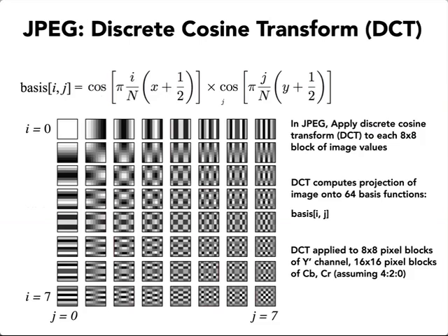So that's big idea number 2 that I described originally: put the compression into luma or luminance rather than chroma or chromaticity, which are equivalent, at least for our purposes today, technically. The other idea I said was that the human visual system is less sensitive to compression error or image error that's in high frequencies as opposed to low frequencies.